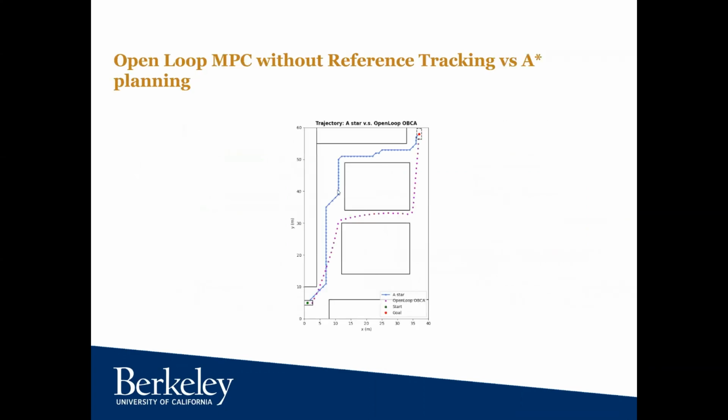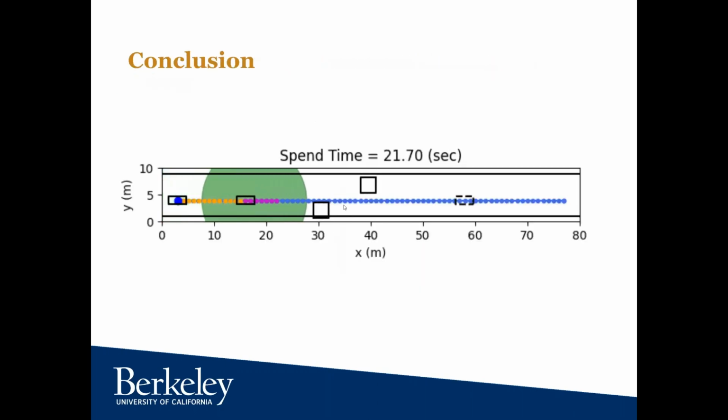and we switch to the second MPC in solving both static and dynamic obstacles. In our interest of getting rid of the reference tracking, we tried to use only starting positions, terminal positions, and MPC to solve only static obstacle cases, but it is interesting that the path chosen is significantly different from the one generated by A-star. We inferred that the distance error comes into the cost function and pushes the MPC to choose a different one. In general, we successfully designed a closed-loop MPC for our dining car, achieving the purposes of reference tracking and obstacle avoidance, including both static and dynamic ones.